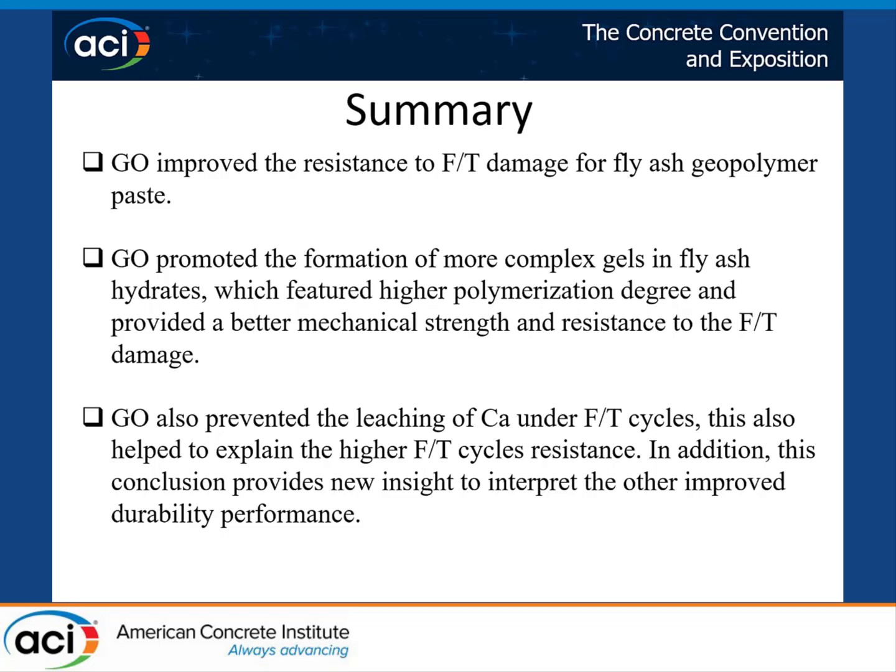But that's our next step. We're adding some water-resistant admixtures, fibers and air entraining agents. I think the performance will increase tremendously. And also, this is just paste, but when we test concrete, of course, with the aggregate phase in there, the performance will also increase.